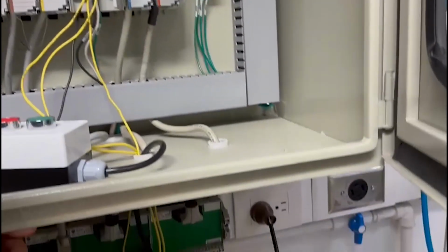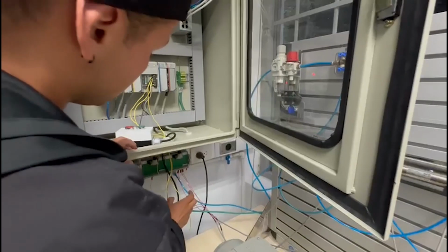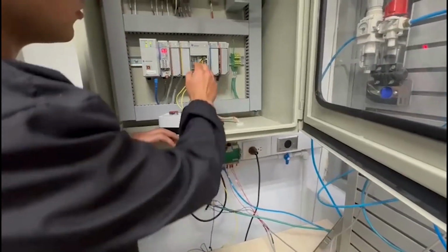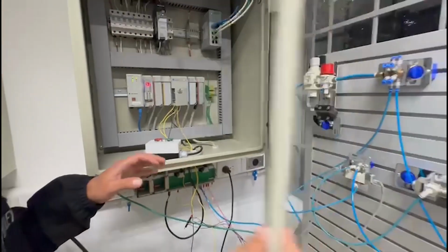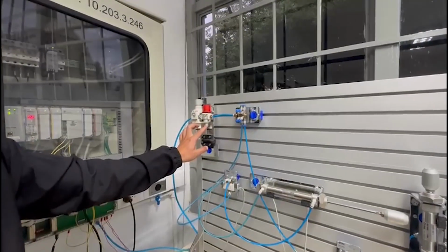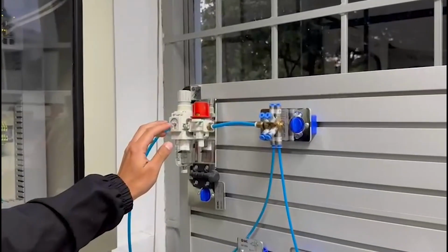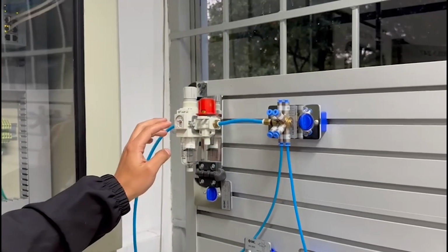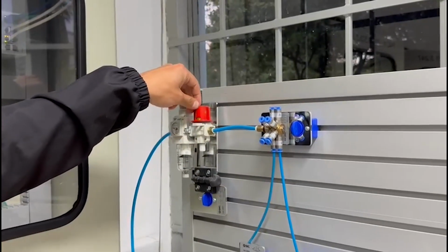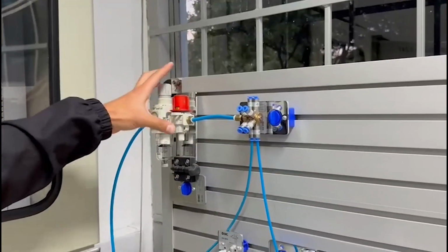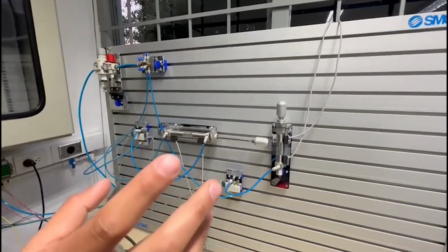Then we connect the inputs of our three relays of the electropneumatic elements, and we close the circuit with the common wire that comes again to the source of the PLC. These elements work with two valves for our control. This valve regulates the pressure air. We have a regulator set for 0.2 megapascals, and this one allows the air to go through into the system. So right now we have the system supplied with air pressure. Now we will show you how this works.